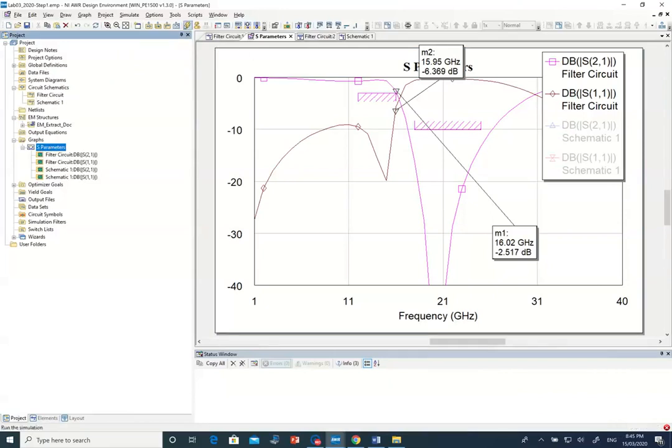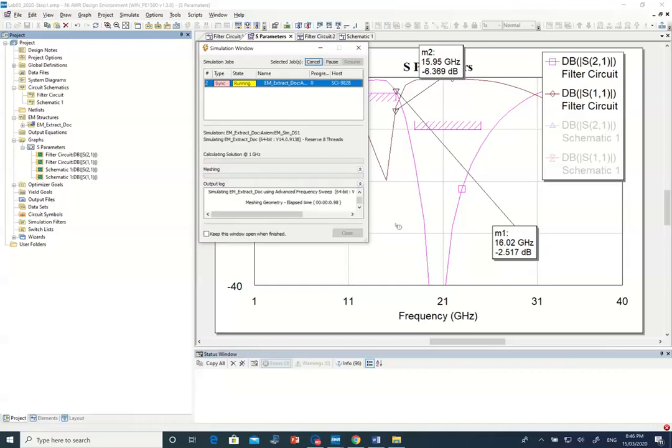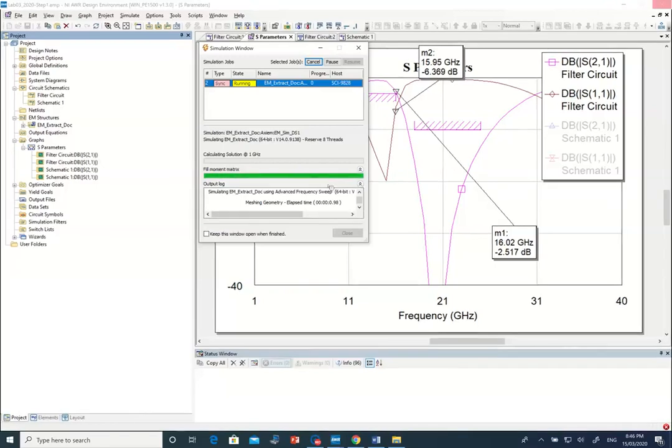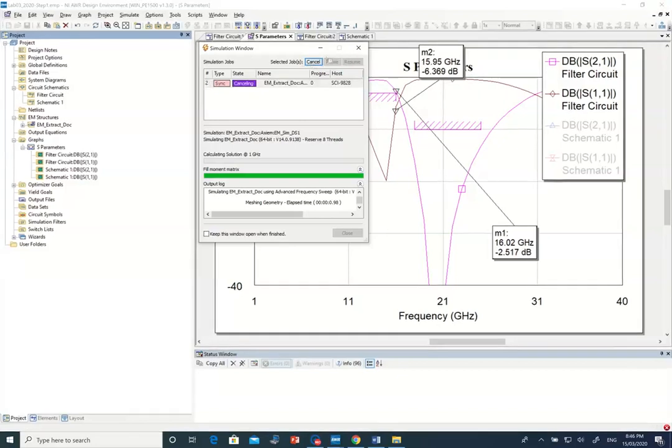So if I run this EM simulation now, it starts running the EM simulation. It will take a while depending on how fast your PC is. It will take maybe 10, maybe it can be 50 minutes. So you make sure, as it might take a while, you do things in terms of reducing the number of frequencies. So one thing that you can do, I cancel this.